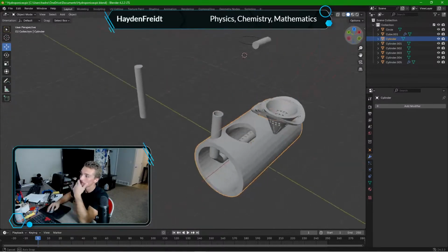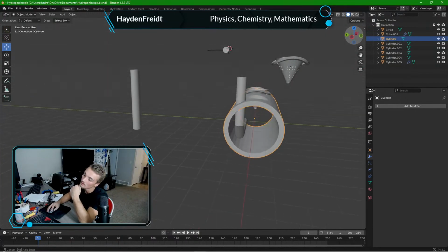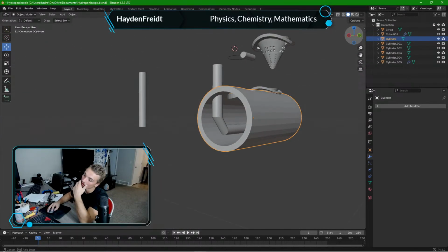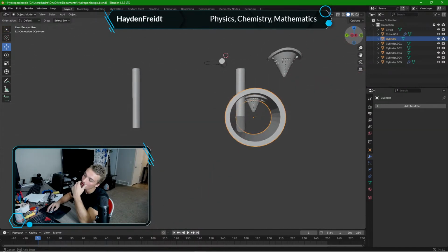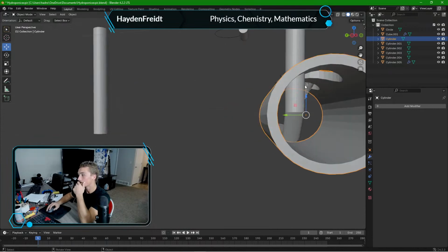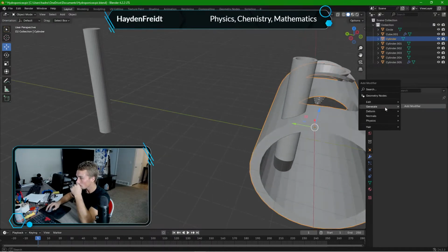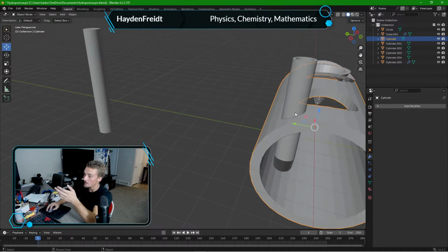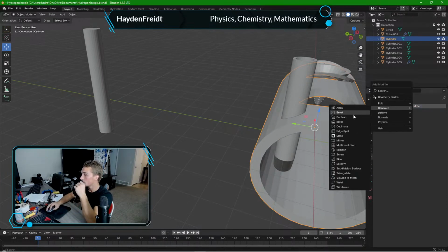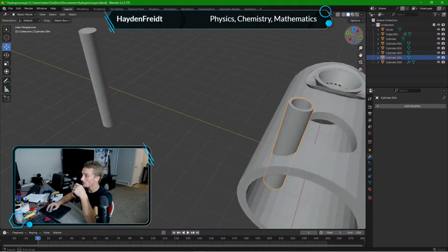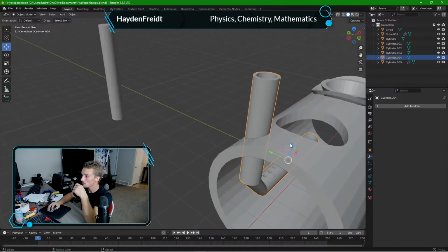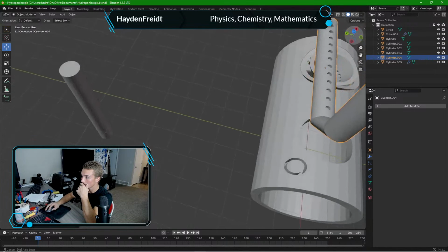It would be much easier to just print it. No. Alright, I'll try to add it into the object. For this, we want a hole here. As of right now, there's no hole where this is going to enter. So generate, Boolean, difference. We're on the big cylinder. We're going to choose him. Apply. And now we got a hole all the way through. I don't really want to move him, but I just want to make sure. And it's like that. Okay.